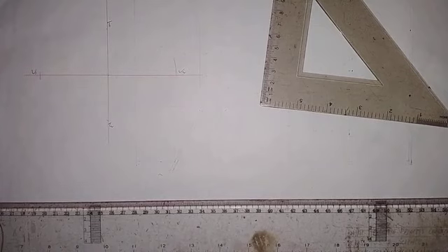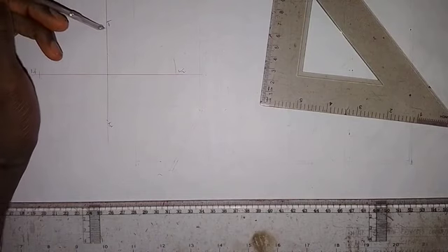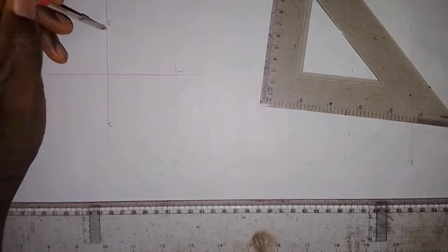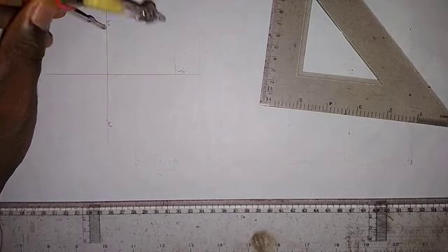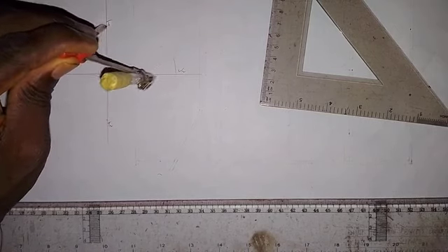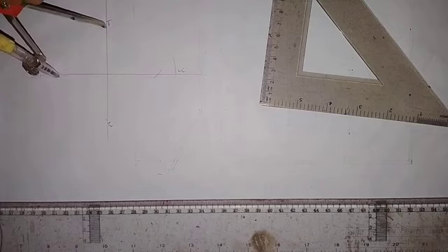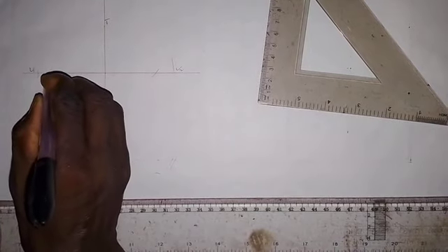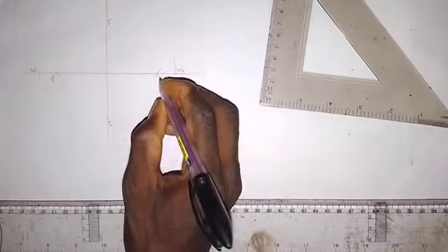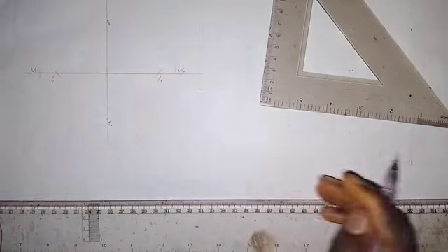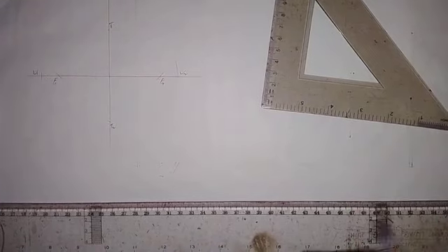So now I will take my compass, that same 60 that I said I'm to keep. I will put it at this point T1, or on point T2. What do I want to do? I want to locate the focal points. So you make an arc here on this line, and then you make an arc on this side, like this. Then I'm going to call this point F1, that is focal point 1, and this is focal point 2 here. So this is how to go about it when you are using focal point method.